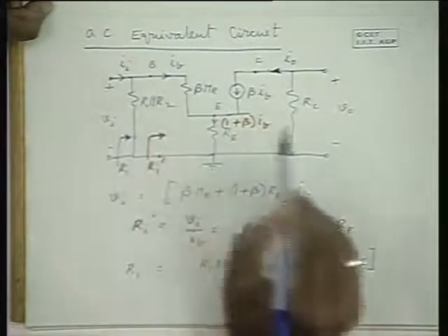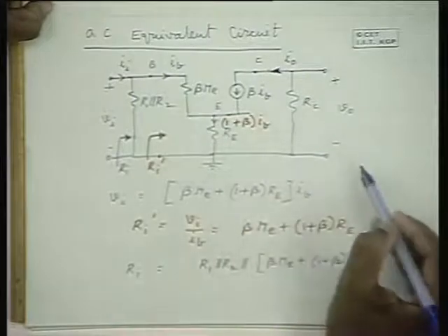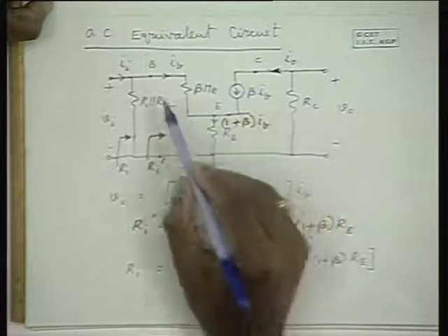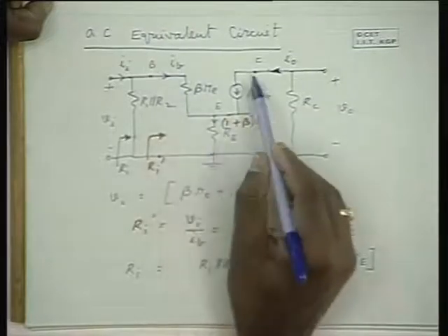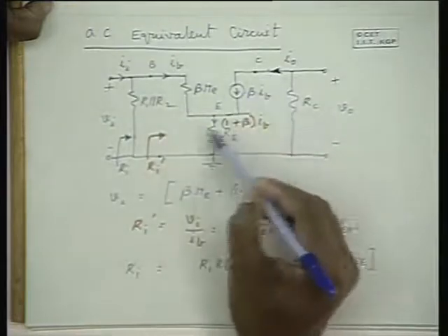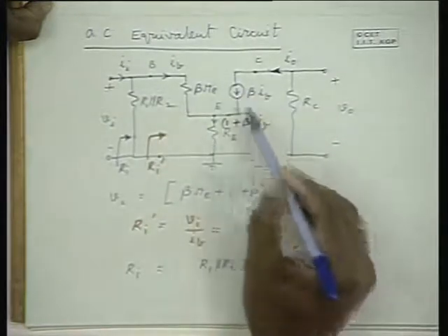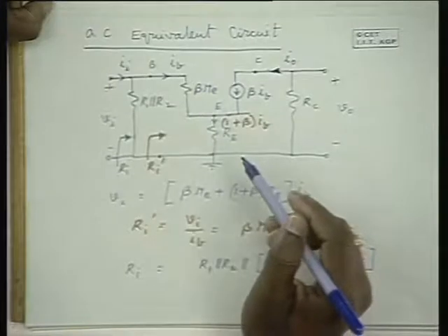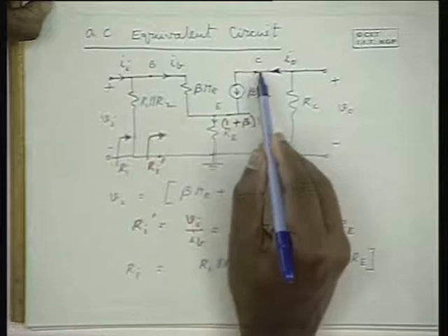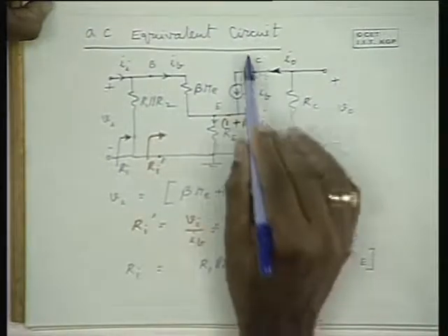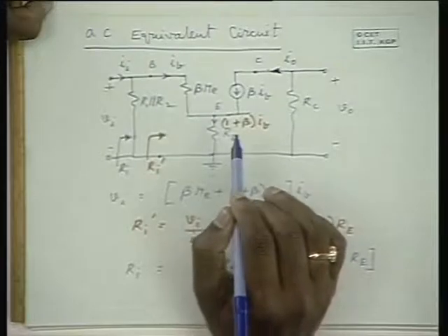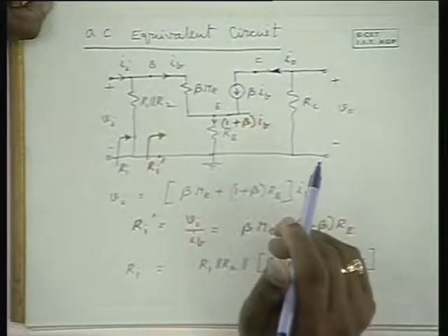Now, if you replace the input over here, please note that there is no driving voltage on this side, and when you apply some driving voltage here, the IB current also would be 0. Therefore, nothing flows inside, no current flows inside. So the current that flows inside is 0. That means it is an open circuit and the impedance is infinity, excluding RC.